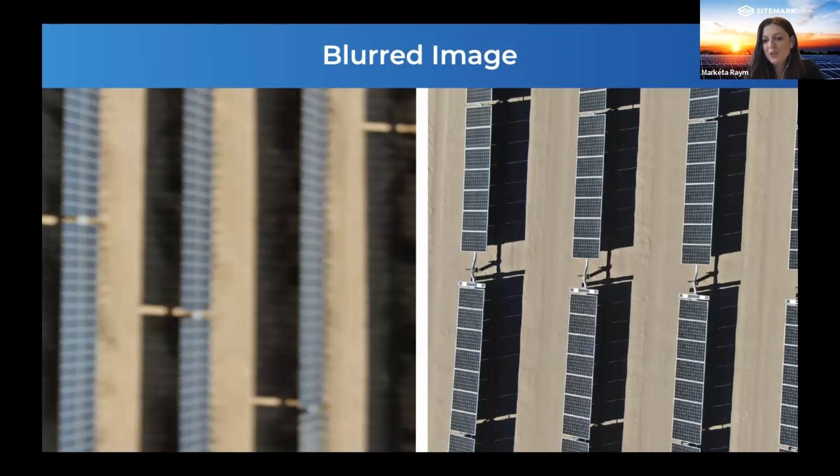Pick up a few random images from the SD card and check the image quality. This is easy to spot and easy to fix while being on site, and not to spot a few days later. It is all about having the right focus, seeing if it's manual settings or automated settings, motion blur or out of focus blur. There are several types, but it's always about having good experience. And once the pilot is really getting up to speed, this is not something that we would expect on the second or third operation.